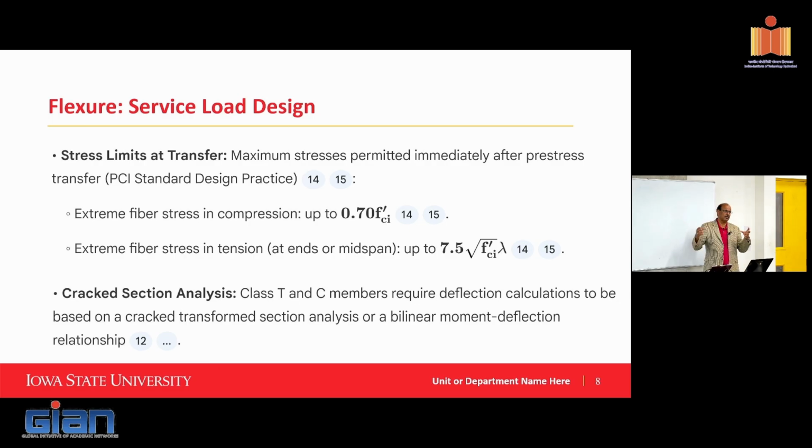They may put this temporary prestressing into the beam. Again, you have to check to make sure it doesn't exceed any of the stress limits at transfer or at service. You take the beam, you place it in. At that point, you can just cut the prestressing and release it so that the beam is now supported at multiple locations and it's not going to be cracked.